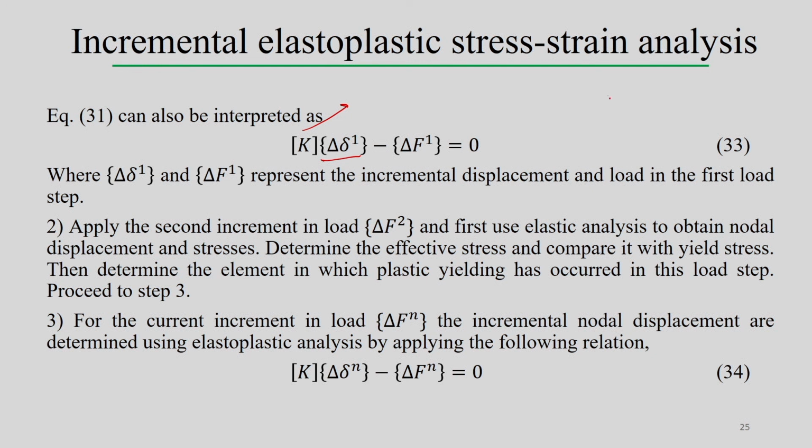Correspondingly, the load vector is not the total load vector; rather, the total load vector we can divide into small increments. Assuming the total load is divided into n steps, for each step we know the incremental load, and accordingly we can estimate the increment of the displacement.